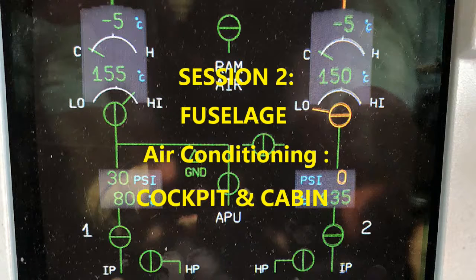And for the ventilation, there's a diagram to give you an idea of the ventilation panel in the cockpit. It's a 22 VU is what the panel is in the cockpit, and it shows you your cabin fan switch, off, on. You've got your blower and your extract on there as well.